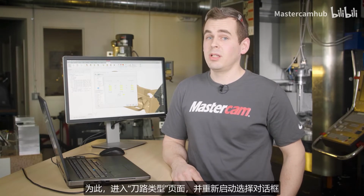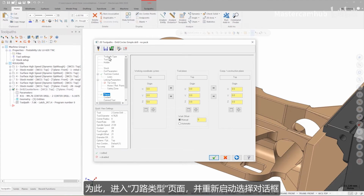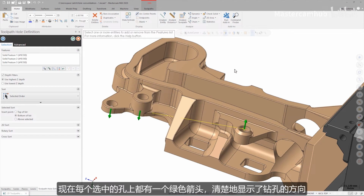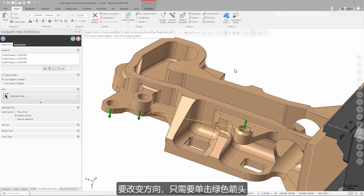In 3-axis, the direction that Mastercam drills the holes from is controlled by the tool plane that's selected. But now that I've changed this to a 5-axis toolpath, I need to tell Mastercam what direction to drill the holes from. To do this, I need to go to the Toolpath Type page and relaunch the selection dialog. Each of my selected holes now displays a green arrow which clearly shows me which direction the holes will be drilled from. To change the direction, all I have to do is click the green arrow. Now let's regenerate the toolpath and take a look at it in Backplot.